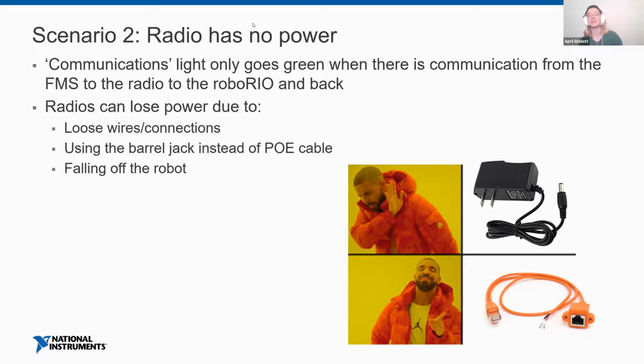Yes, so all joking aside, the barrel connectors had their time and place. They were great. We have something much better now, which is PoE injection. PoE is power over Ethernet, and essentially that powers your radio, but it also has the security of clipping in on that Ethernet port. And so you put those two little terminals into your voltage regulation module, you plug the Ethernet end into your radio, and then your Ethernet cord goes from your RoboRIO to that Ethernet jack there.